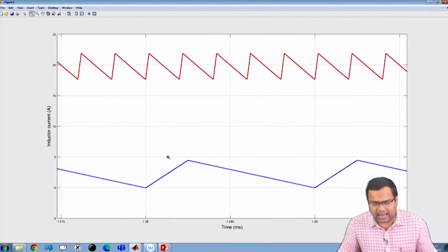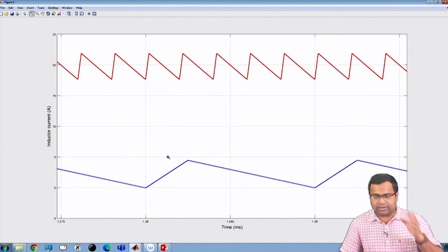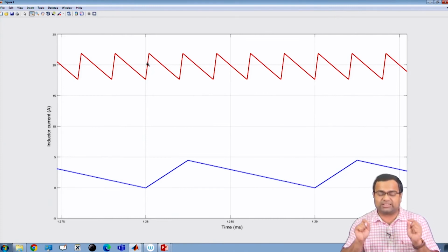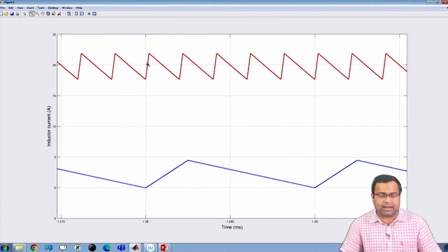Okay. So, here I am showing, if you see the waveform, the top one is the POL inductor current. Since I want to regulate the POL output to 1 volt and my desired output power is 20 watt, my desired output current is 20 ampere. So, you can see the average inductor current is closely 20 ampere. That means we are achieving that desired current using this POL converter.